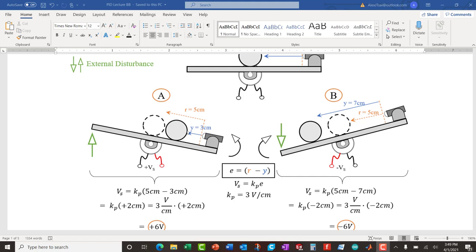It overshoots and then comes back and undershoots and keeps oscillating. That is not allowed. If it has to oscillate, make sure that it does so within a certain amount of time, within half a second. That's called the settling time. And all these time parameters, that is something that we factor into this gain.